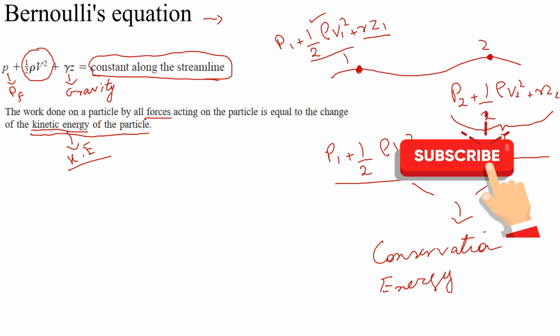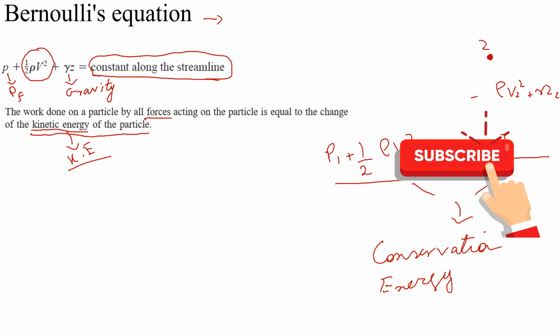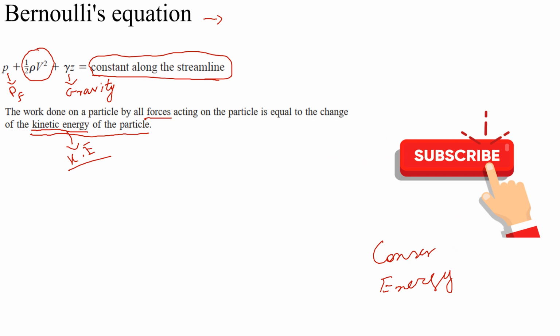So overall, the Bernoulli equation is the equation of motion for fluids, and fluids move by either a change in the pressure energy or a change in the potential energy of the fluid. Or if we talk in terms of forces, due to a change in pressure forces and gravity forces, we can change the kinetic energy of the fluid. So in short, this is what the Bernoulli equation states.